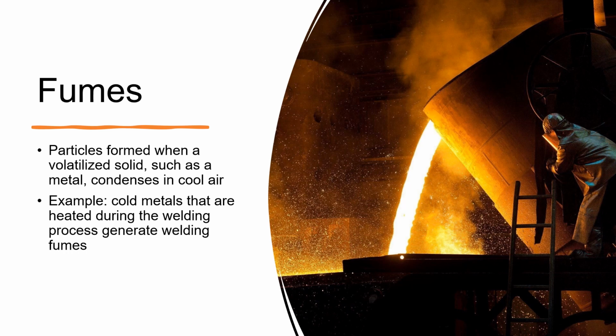Fumes are particles that are formed when a volatilized solid, such as a metal, condenses in cool air. This physical change is often accompanied by a chemical reaction, such as oxidation. For example, when cold metals are heated up and melted during the welding process, this generates welding fumes. In our lecture about non-ionizing radiation, we learned that one of the hazards of welding is the light that welding workers are exposed to.